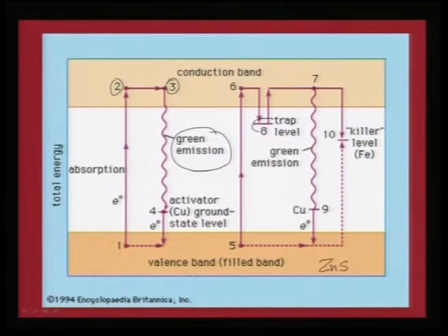There are other things that are also accompanied with it because of several processing issues. One is, if it is a defect induced one, then the electron gets trapped momentarily in this trap level, and because of the influence of the cathode ray, they do get ejected out, and finally they return giving a green emission. So, there are trap levels, and the number of trap densities or trap levels do control the quantum efficiency and the purity to some extent.